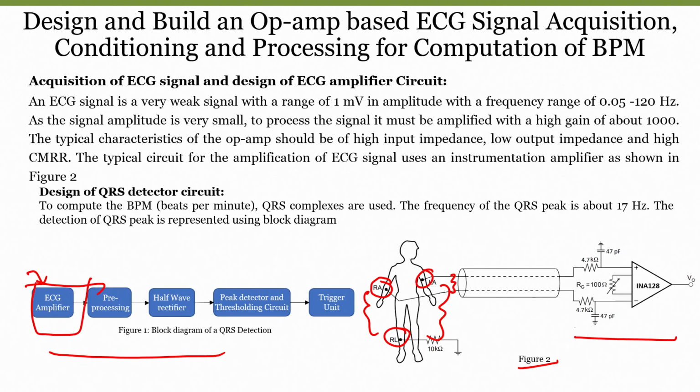Of course, an instrumentation amplifier uses differential amplifiers inside, but we cannot go with a simple differential amplifier because it has very low CMRR. Moreover, the input impedance of the instrumentation amplifier is very high because the input is directly connected to the non-inverting terminal of an op amp, since the instrumentation amplifier is made up of a 3 op amp based circuit.